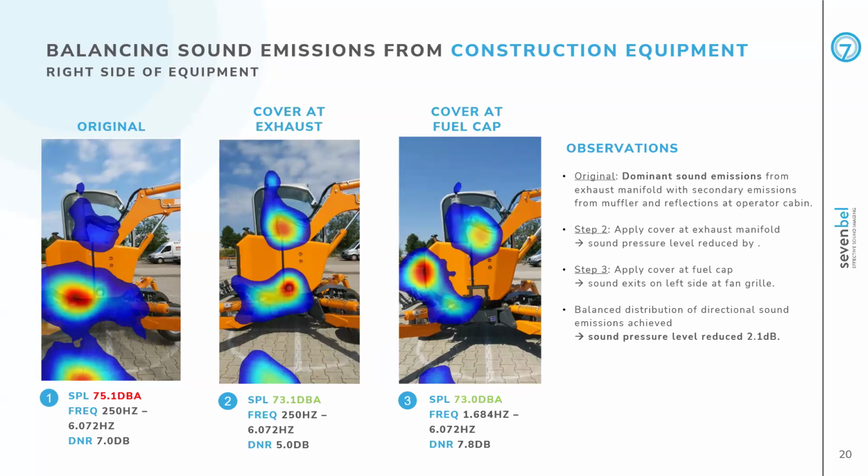So if we did that measurement with a smaller acoustic camera, with smaller measurement surfaces, those heat maps that you see, or the sources that you see and the distribution of those sources, would be much more spread out. This source here would eventually stretch up to the top of the cabin, and all of the sources start to blend and overlay. In the end, you will have the impression, okay, great, I found my construction equipment, but you don't get the required spatial resolution, meaning resolution in space, in order to uniquely identify where certain components are emitting sound.